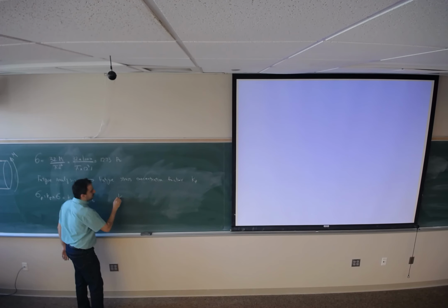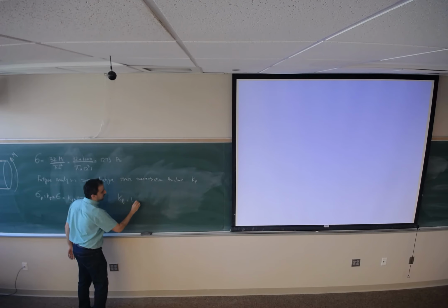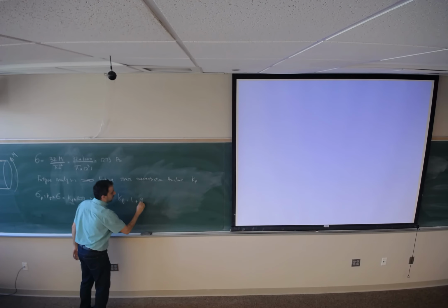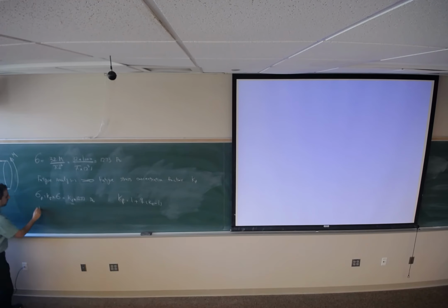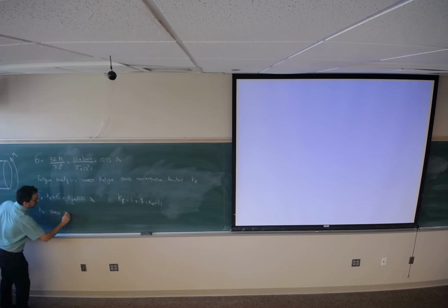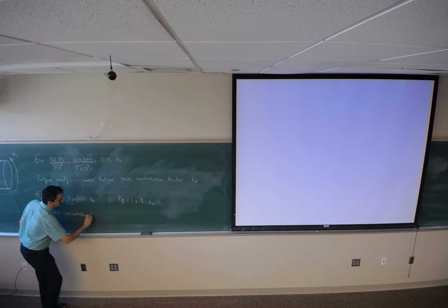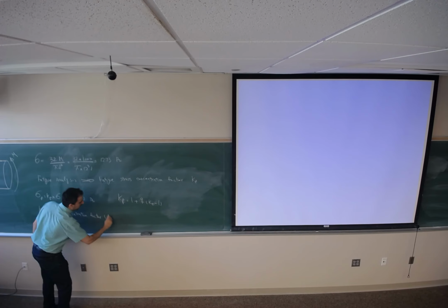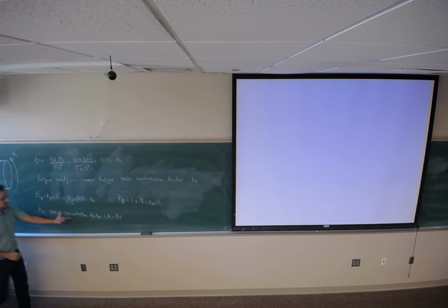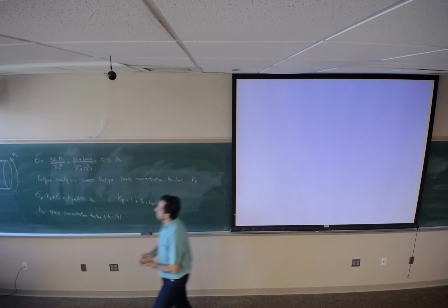Fatigue concentration factor is a function of Kt. Kt, if you remember, was the static stress concentration factor. Table A15: depending on the geometry of the component and the loading, you can find Kt.